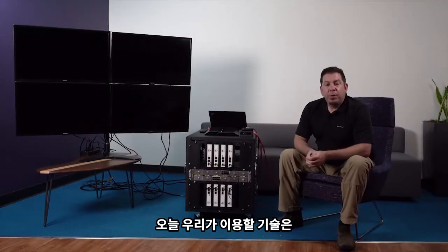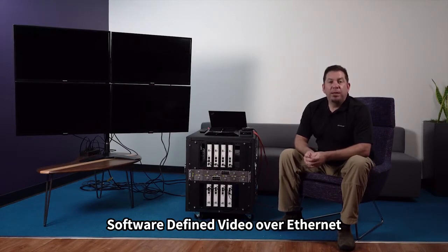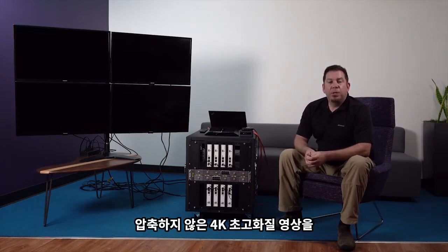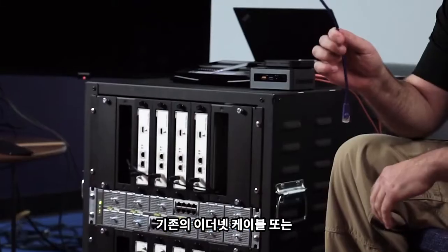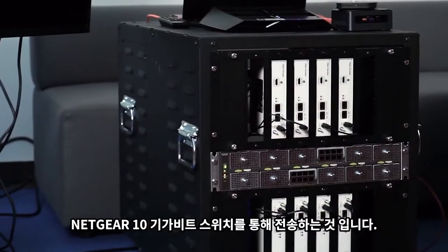So the technology we're going to be using today is what's called SDVoE, Software Defined Video over Ethernet. What this technology allows us to do is to push uncompressed 4K high-def video using standard copper Ethernet or fiber Ethernet cabling through a Netgear 10 gigabit switch.